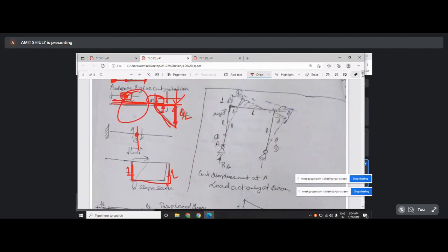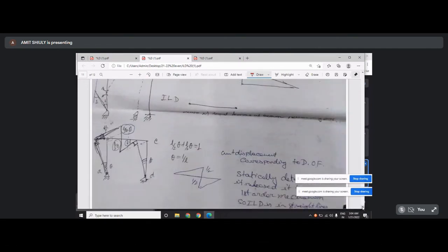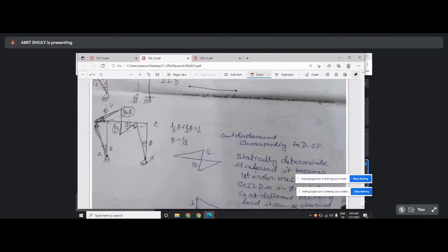So give a unit deflection. Suppose here I have unit shear force. I have cut this section. This is unit, and this is the deflected shape. This will remain 90 degree, because according to definition, this is a rigid joint.